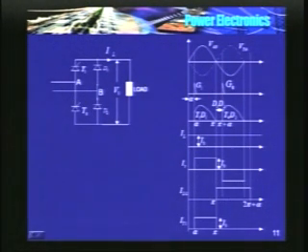So if I plot the duration of diode conduction with time, you will find that D3 starts conducting at pi and continues to conduct till 2 pi plus alpha. Please, this should be ID3. I am sorry about that, it should be ID3.